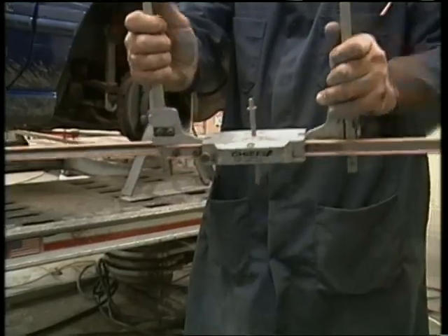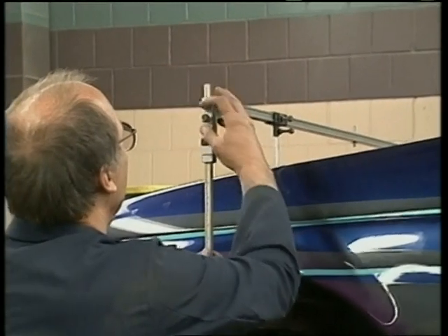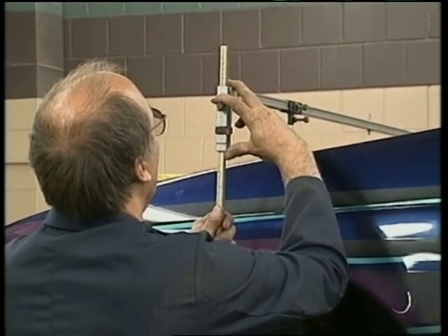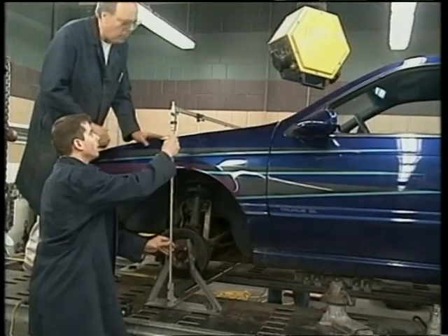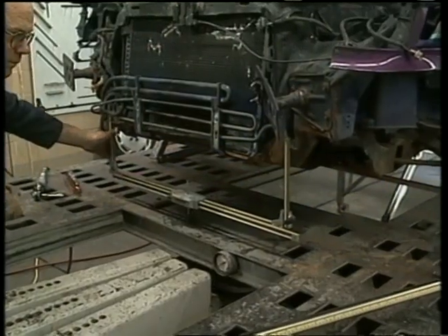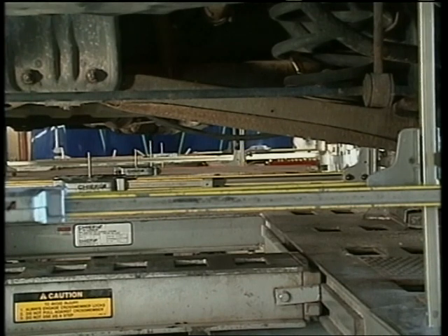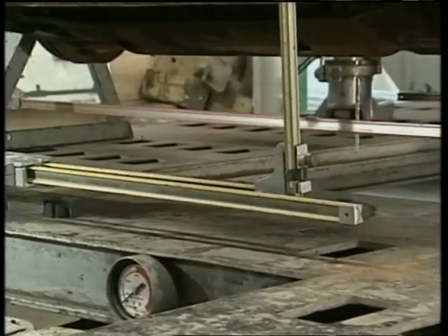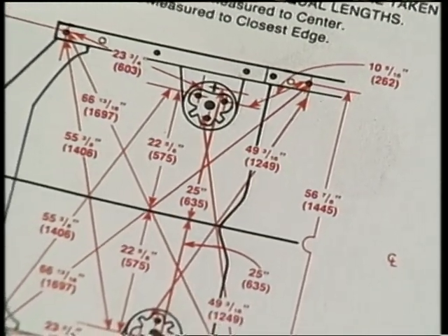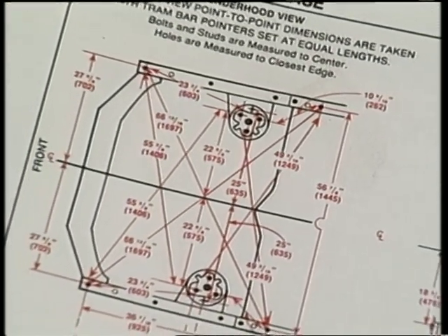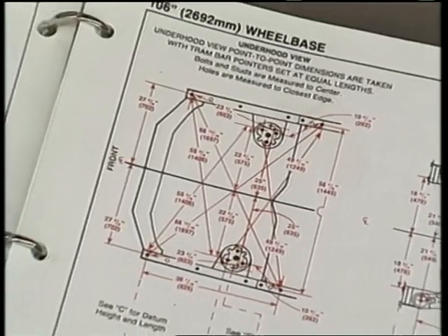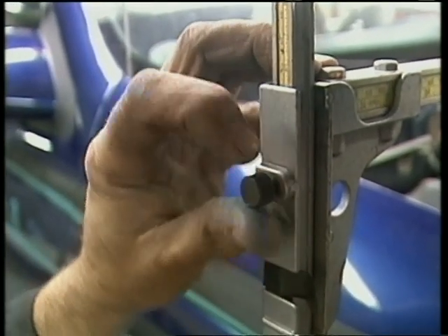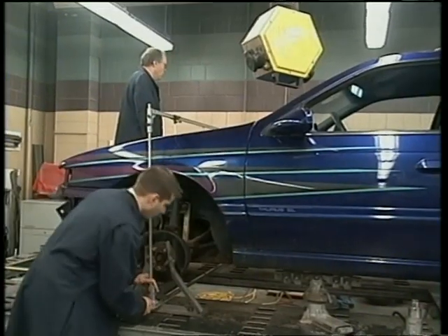Self-centering gauges show alignment by projecting points on the vehicle structure into the technician's line of sight. Self-centering gauges are installed at various control areas on the bottom of the vehicle. They're used in sets of 4 or more to establish the vehicle centerline and datum plane. A body manual will give information for adjusting them to hang on the same plane under the vehicle. Scales are provided for adjusting the gauges to hang at the correct distance under the vehicle.